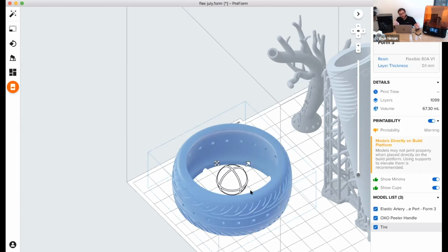With elastic materials, with flexible materials, with any soft material, it's more of an issue because it's so much more compliant in that green state, so much more compliant while you're printing. And so there's a very real chance that you can pull it in that direction. The whole thing's going to move.